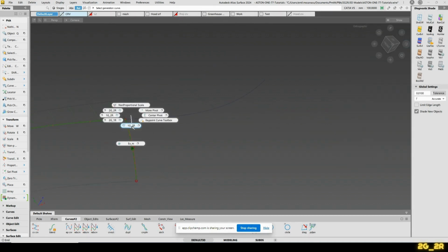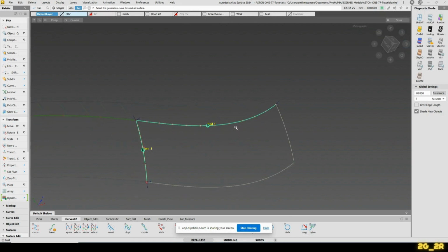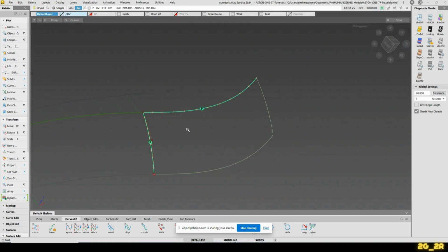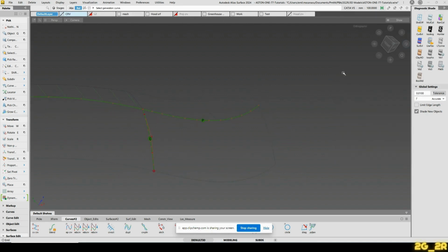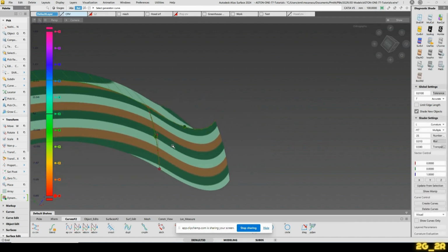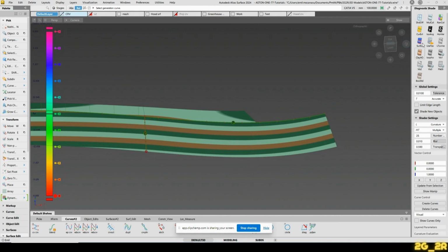And then I'll use that monorail edge there, that curve, to generate this bit there. Since that curve is aligned with curvature to this one, we can go ahead and generate with curvature turned on. It's going to work. Turn off curve segments because I don't like to have it going through. And let's do that.